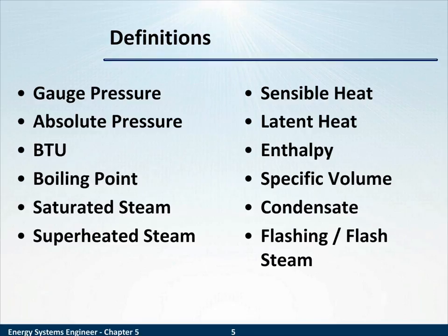Sensible heat and latent heat we've discussed as well in the HVAC section. But think of it this way. Think of sensible heat, sensation, sensing, feeling. It is the felt change in temperature. The latent heat is heat that causes a change of phase without a change in temperature. You'll see that on the graph as well with saturated and superheated steam. But sensible, the change in temperature; latent, the change in phase. Remember that.